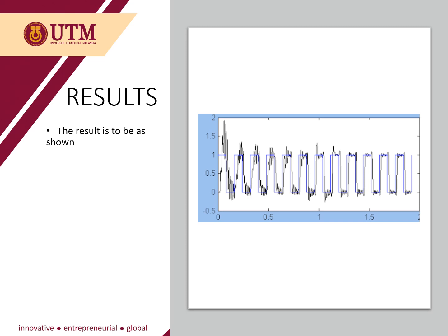Due to the complexity of the CMSIS DSP functions, the project was not able to be finished. The main code that consists of the CMSIS DSP functions has issues with the library being initialized with multiple types of floating point through the -mfloat-abi command, which requires both hard and soft for this particular project. However, the IDE compiler does not support both. The project should be enabled through Keil software to support this.